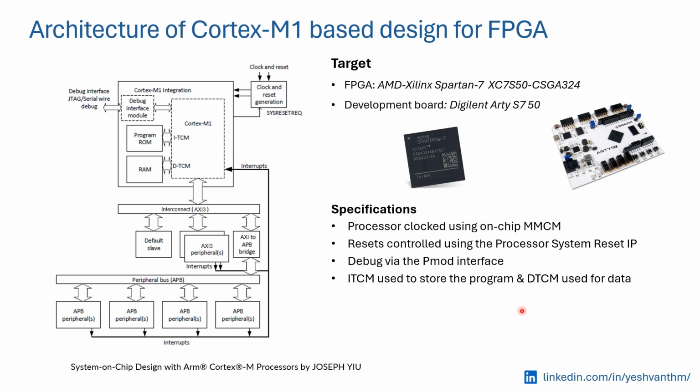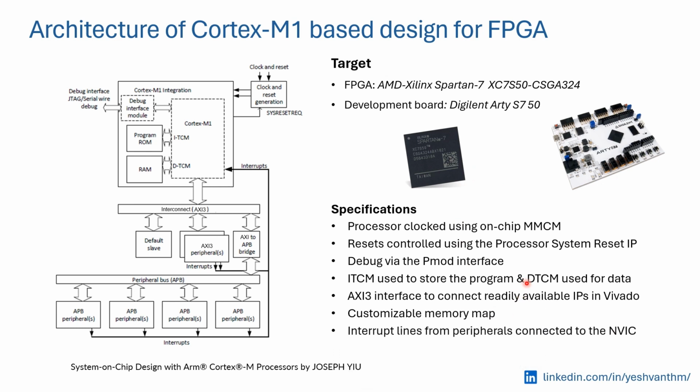ITCM is used to store the program, and we use the DTCM for the data memory. And an AXI3 interface to connect readily available IPs in Vivado. You can see we have an AXI interconnect here. A customizable microcontroller memory map, but we still have to adhere to the standards of the core, whichever is specified in the datasheet. The interrupt lines from the peripherals are connected to the NVIC.